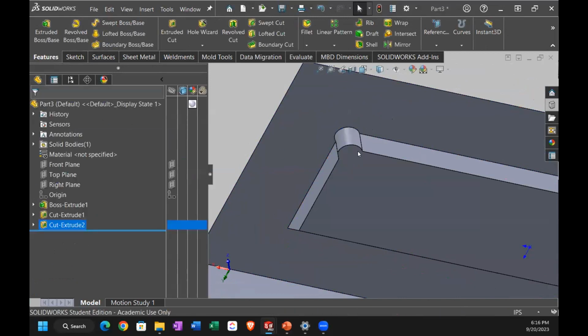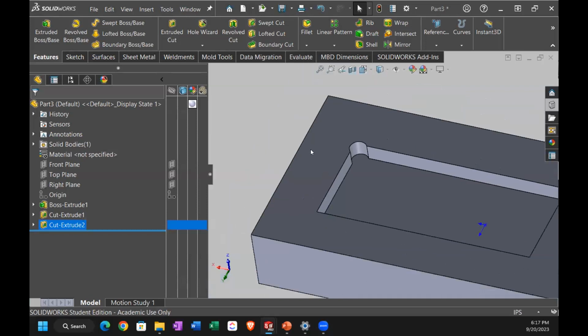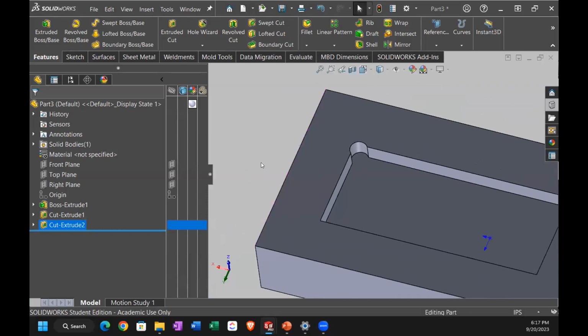Now, when I did the experiment, I always think, wow, it'd be great to put in a couple of fillets so that this becomes tangency. So when I apply my toolpath, the toolpath says, oh, I can go all the way around this thing. I don't have to do any other selections or see it change direction. Well, when I added the fillet, it just made it more complicated. It was a lot easier to put this geometry in and add fillets or additional features afterwards. So again, keeping it simple, just what I need.